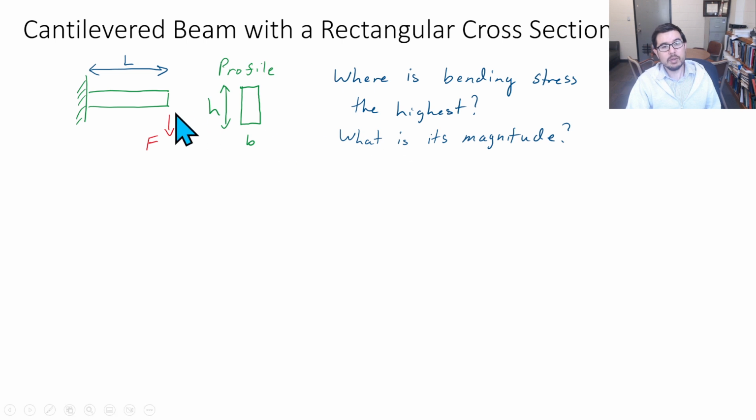Well, let's go through the exercise again of first calculating what the bending moment looks like across this beam. And to do that, we would first perform external equilibrium, whether you use equilibrium or you use integrals, to graph this profile, we need to start with external equilibrium.